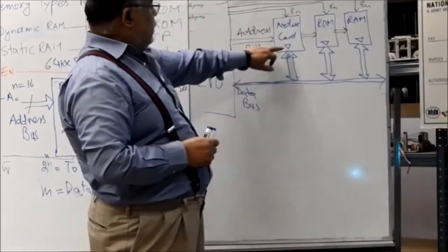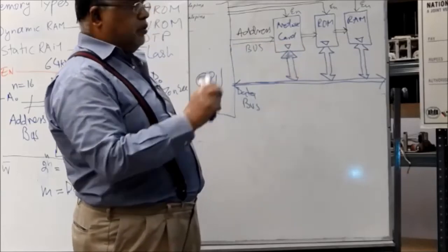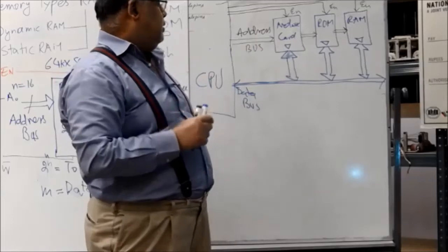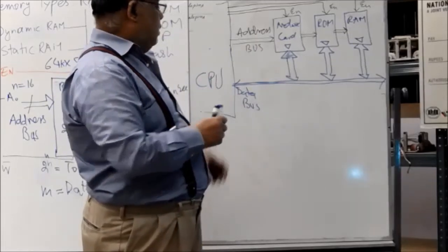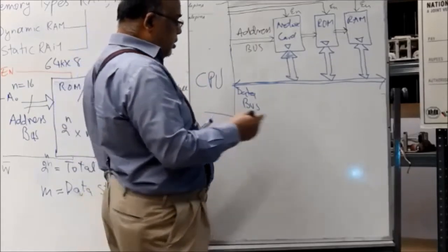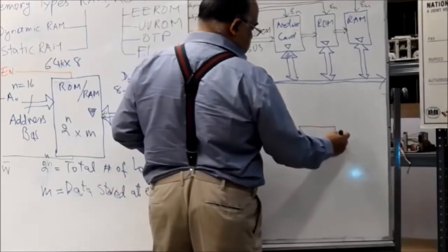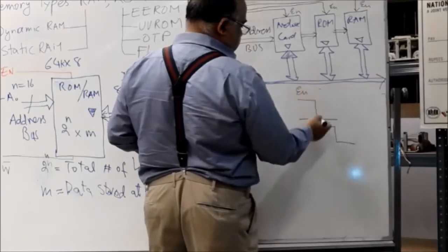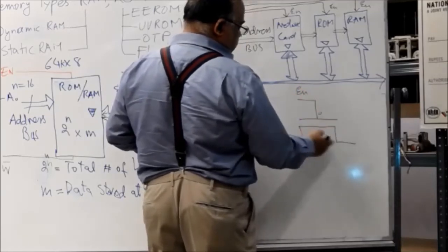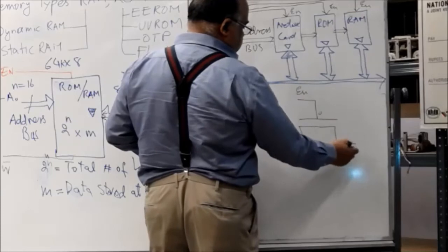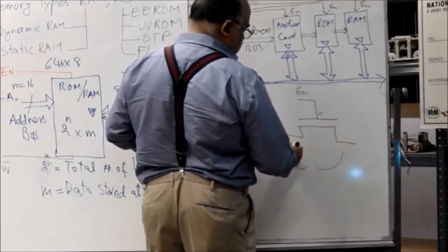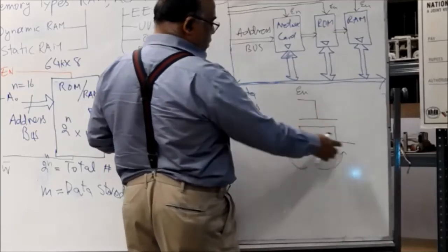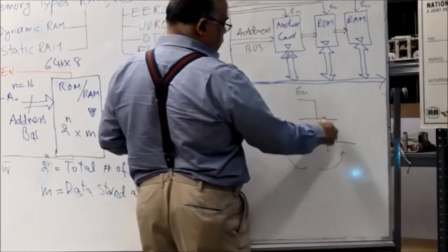So these tri-state buffers can switch things off and on, just as if they are not there. Basically, they are simple transistors like this. Enable. When enable is 0, the transistor connections are at very high impedance. When enable is 1, it is a short circuit. Current can flow from here to here or here to here.